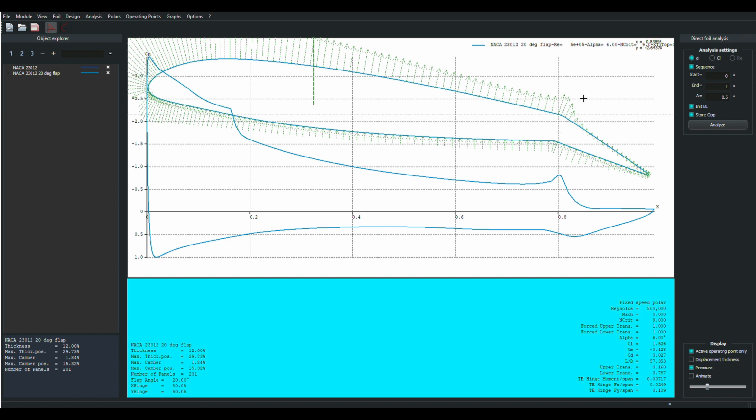So it's a trade-off. So we've got the same data here, the pressure distribution on the airfoil, and then the plot of that pressure distribution. And we note that you can't see it here, it's off the screen, but these pressure vector arrows are much taller. We're generating much more lift up front, and all of the arrows are taller back here, so the adverse pressure gradient slope is about the same, but it's a little bit more spread out.